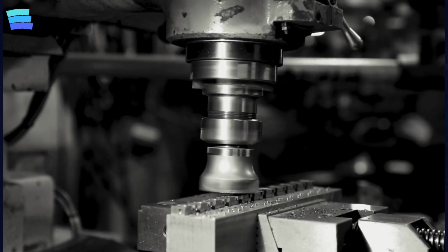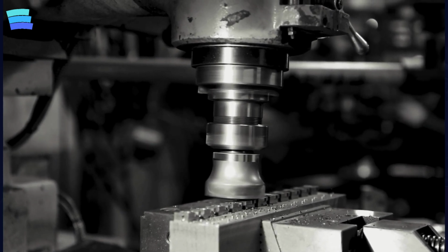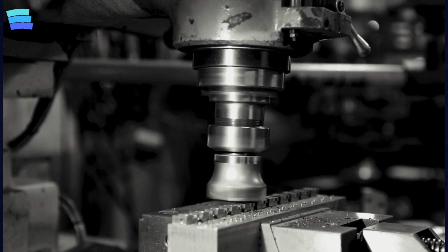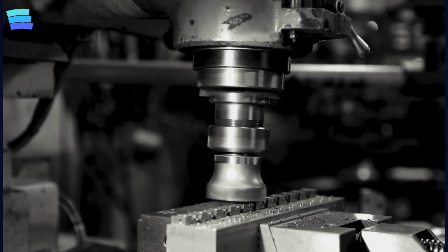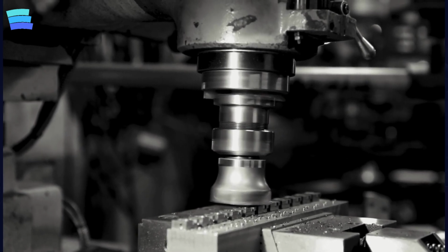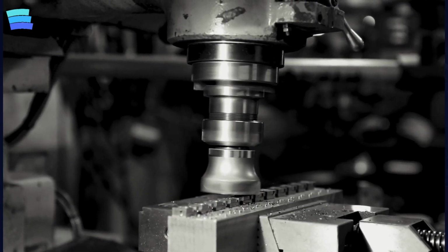After this video, you will see much more clearly how a small detail on a drawing can turn into an entire operation chain in milling. Because in milling, the biggest cost driver is often not the amount of material removed. It is how many times you must clamp the part, which surface you choose as the reference, and how many measurements you are forced to insert between steps.